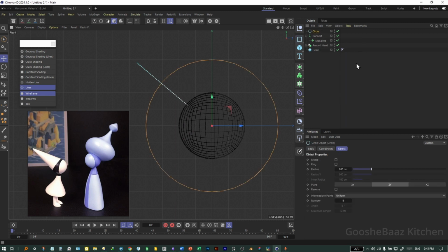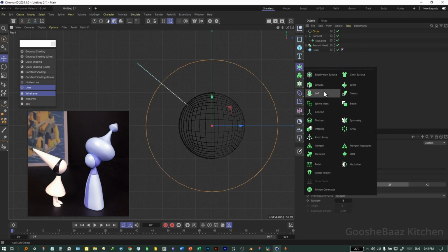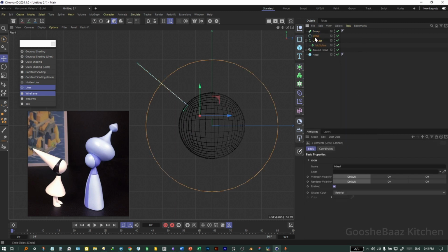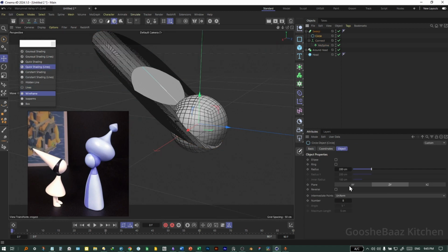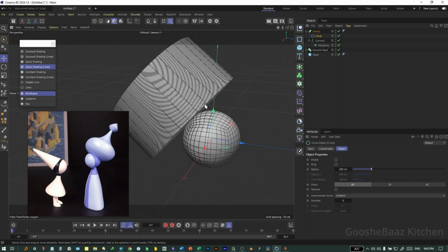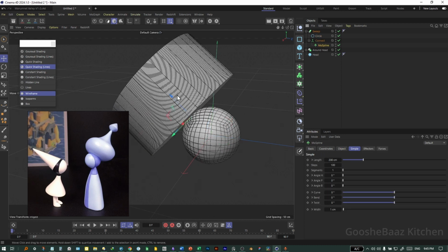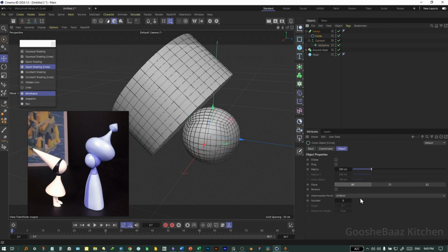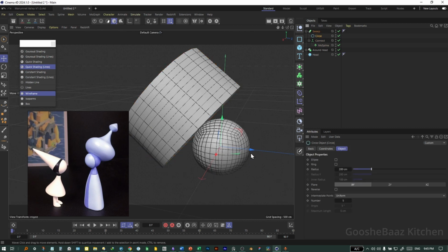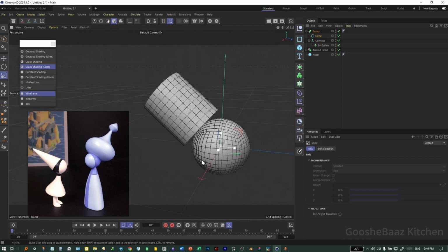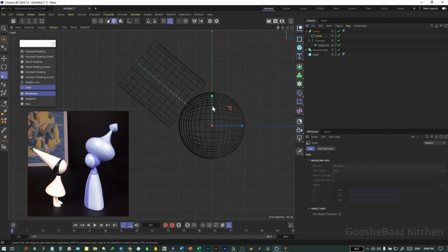Now add a circle spline, then add a sweep object. We put the connect and circle as a child of sweep. Click on circle, change the plane to get something like this. Come back to mouse spline, decrease the step to decrease the mesh density. Something like 10 is okay. Come back to circle, you can also decrease the density for a circle. Okay, let's come back to circle, T for scale, decrease the size, come to side view, that's okay.